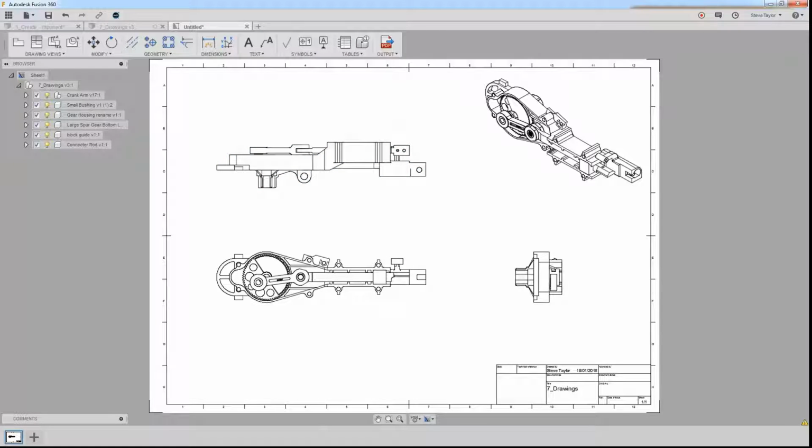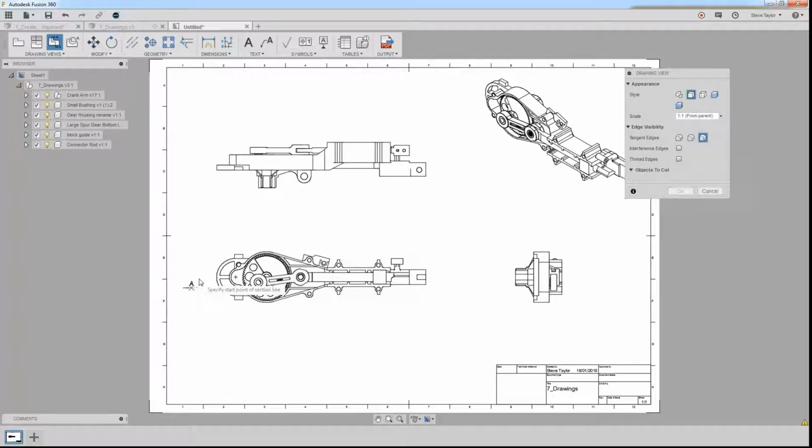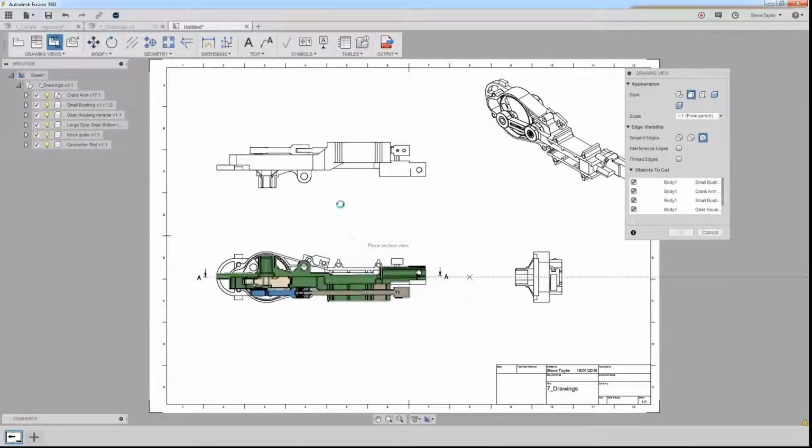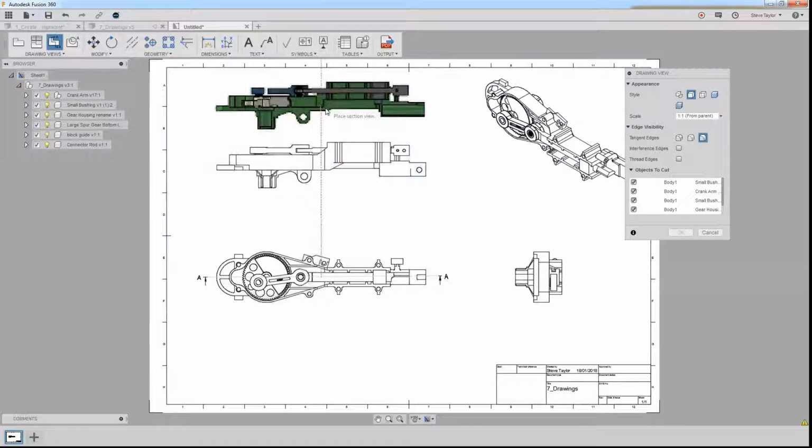We can create a section view. So I wanted to create a section view of this. Again, sectional views. Again, select my parent view. This time it wants to know where I want to make my section through. So I could do a stagger, but for this I'm just going to come across, select, right click, continue, and then what I'll do, I can pull this up there,